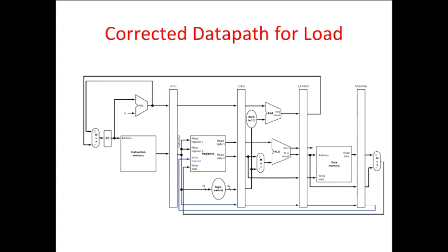But notice you only need in each pipe stage the control decode for the stuff that happens in that pipe stage. So at the end, you just need to know, am I writing a register? And if I'm writing a register, which register is it? So in practice, what happens is as this goes down the pipeline, some of the bits drop off because you've kind of done that piece already. You just need to keep the control bits for the remaining pipe stages, right, as you shift down the pipeline.